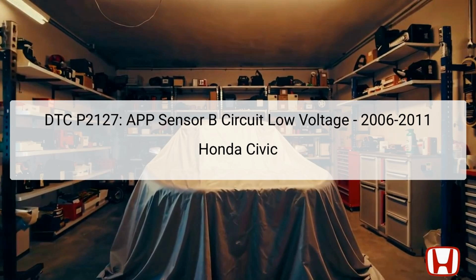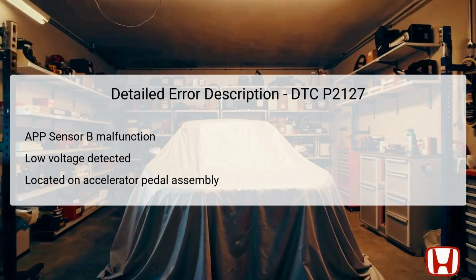The error code P2127 indicates that there is an issue with the APP Sensor B, specifically related to a low-voltage signal being reported to the Engine Control Module, ECM, or Powertrain Control Module, PCM. This APP Sensor B, also known as TP Sensor E, is integral for accurately detecting the position of the accelerator pedal during vehicle operation. In the context of the 2006 to 2011 Honda Civic, this sensor can be found on the accelerator pedal assembly itself, nestled within the footwell.